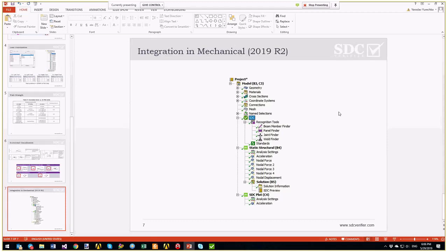We can recognize the welds, and if you put a thin sheet on the outer boundaries of your volumes, you can do fatigue checks on the surface as well. So in case you have fatigue cracks in a solid model with welds in there, that is a good option to have. I think we will add a webinar on solid models somewhere at the end of the year or something.